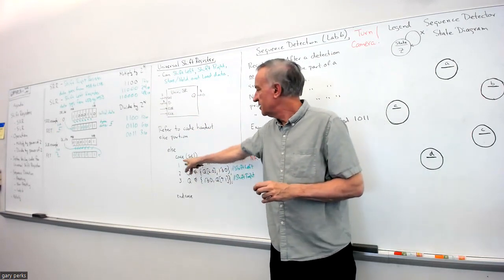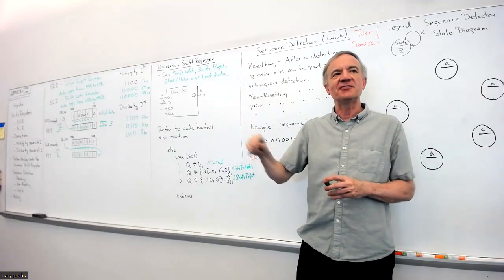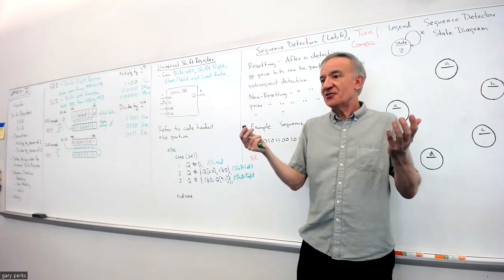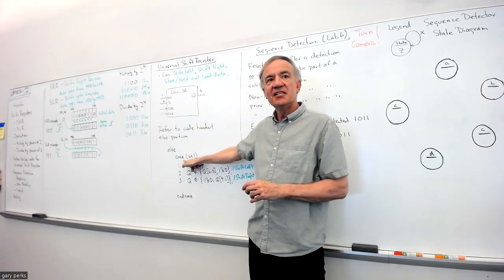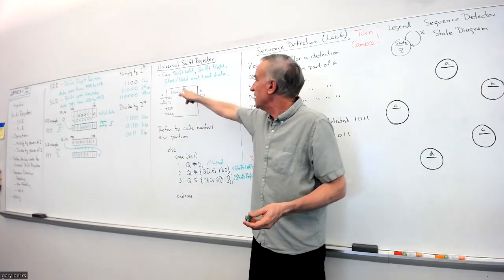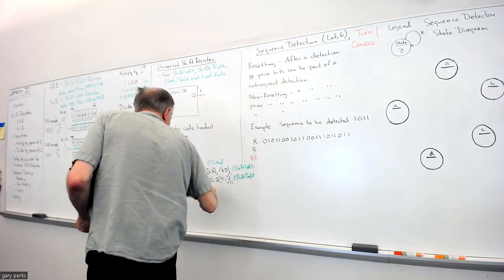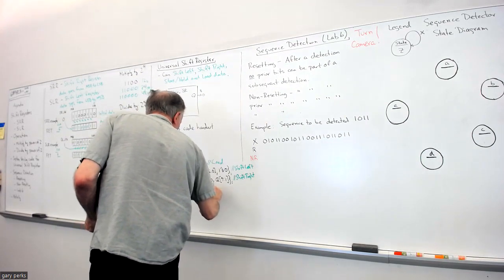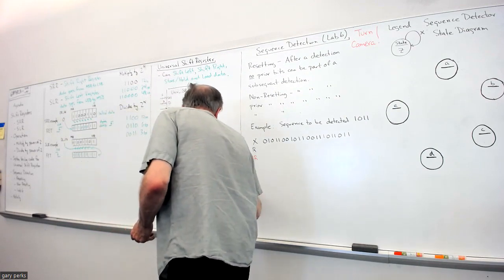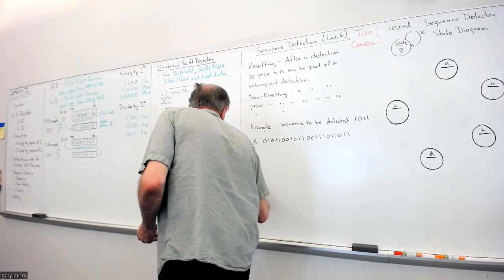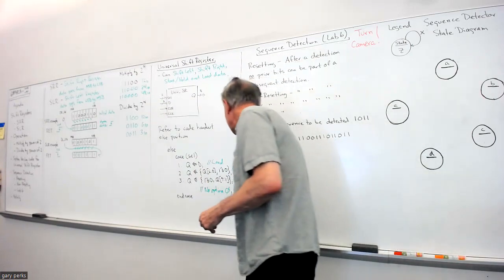What's going to happen if I don't have a complete case statement? What happens if I don't have a complete if, like if I leave out the else? Yeah, it creates a latch, which is the memory, right? That's the storage. So same thing here. By leaving out the 0, that means that's the storage. That's when the hold happens. Okay, so you see, there's no option 0 because that's going to create the storage. It creates a latch, which creates the storage. Okay, so that's your hold state.